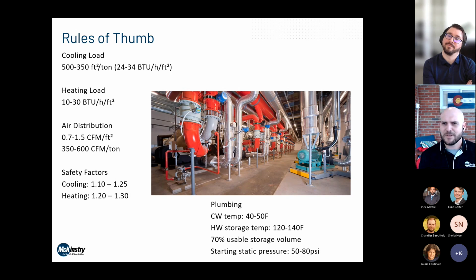I think the U.S. average is probably in the 400 to 450 range, and I have seen loads as low as maybe 700 square feet per ton, but that's in maybe Aspen, Colorado, where it doesn't get all that hot and it's definitely not humid. So there's a bit of range there, but that's a starting point.